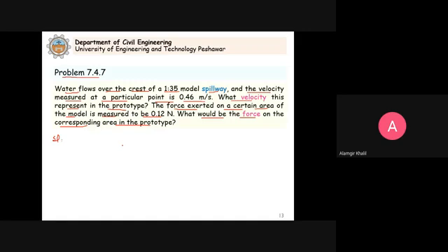So you see that if you consider the Reynolds number, we still have the velocities. You can calculate the velocity from there. If we consider the Froude number, then in that case, again, it links the velocity. So now you see the first step is to determine what dimensionless number you have to consider.